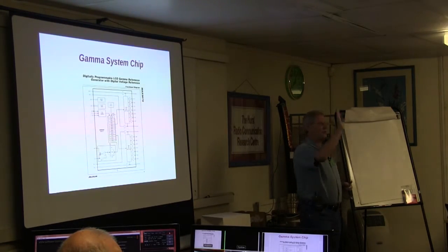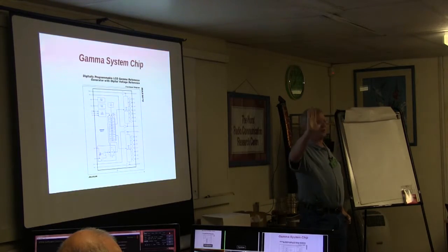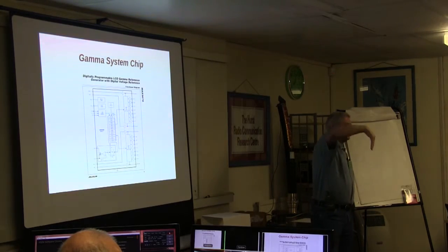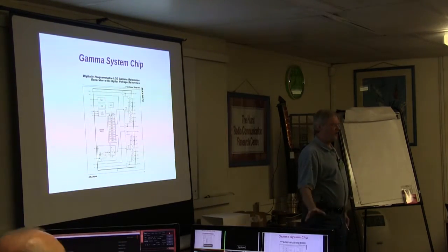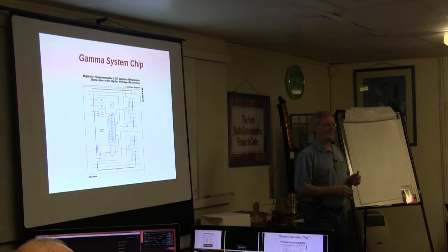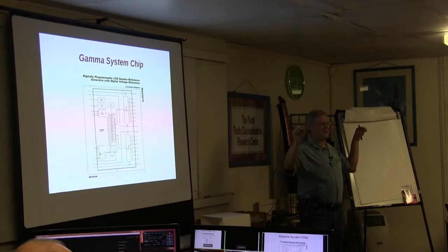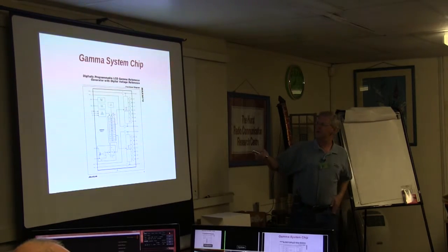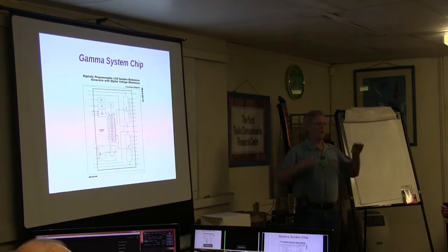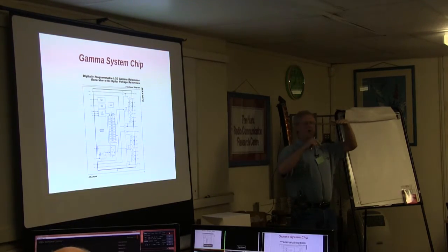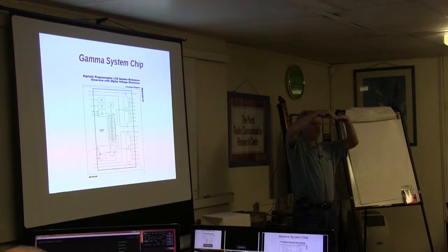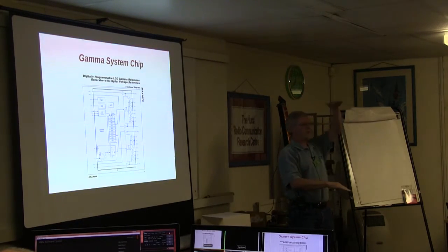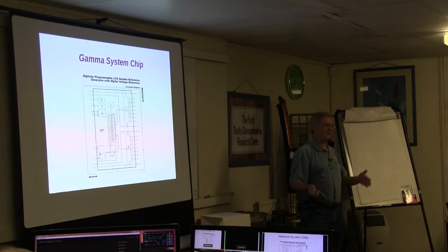So to prevent that, what they do is they put a positive voltage on the LCD, say one frame, and then the next frame, let's turn it over and put the same voltage in the opposite direction. Not quite that simple, but that'll do for now. It gets complicated. They do it pixel by pixel or 3 pixels by 3 pixels and so on. But we do have to invert the polarity on a repeating basis. So the easy way to do that was we had upper voltages which went from a fixed voltage upwards. We had a set of lower voltages which went from the fixed voltage downwards. It doubled the voltage range needed, but it was the easiest solution.